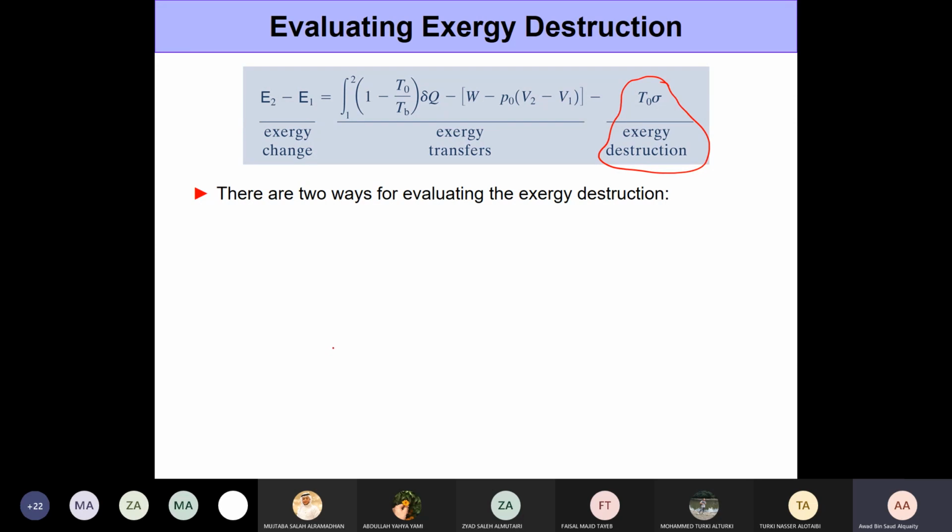But the goal is always to figure out which are the different ways that are acting as the leak points, right? Where are we losing energy to things that are not useful for us, that's not important for our eventual goal. So Exergy destruction is something that we always calculate for any given system, and it allows you to figure out in which component you are losing more Exergy, and then you can make a decision whether it's economic to reduce the Exergy in that particular component, or you should look at some other components, right?